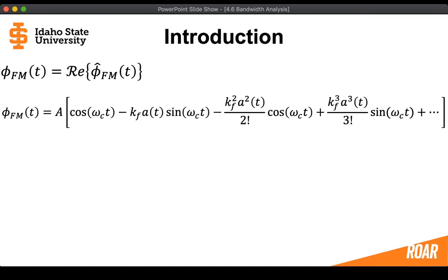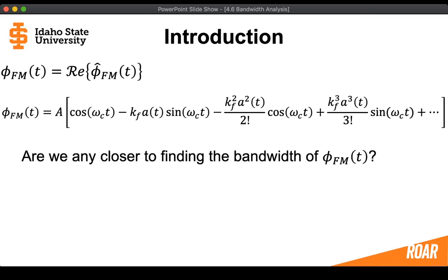All right, so this is starting to look a little bit better, right? Because now we can see that we have a whole bunch of terms, and in those terms there are cosine or sine waves that contain the argument omega_c, which is the carrier signal, and in front, the amplitude of these is now that nonlinear part.